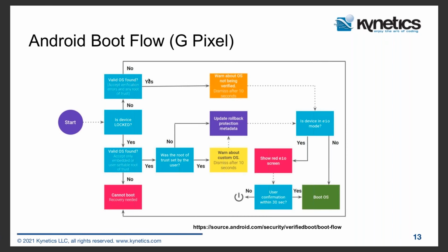Gary showed this image, probably now it makes more sense to you. Basically, a production image should always be locked, and you don't want anyone to actually inject other images on your system that are not signed with your keys. And so one of the things is for a production system to be locked and of course implement a sort of chain of trust.